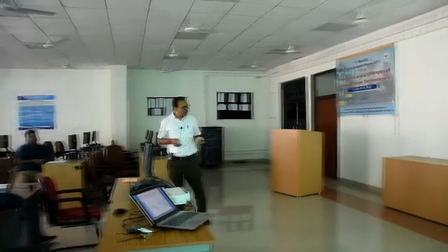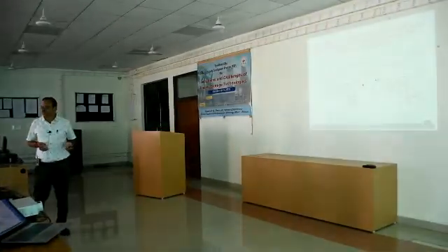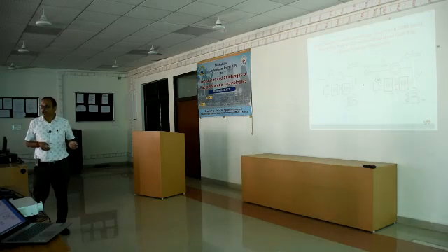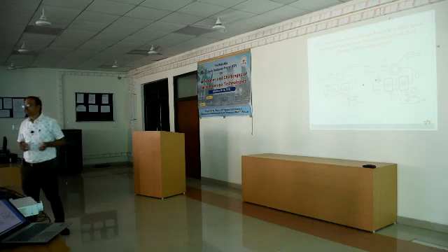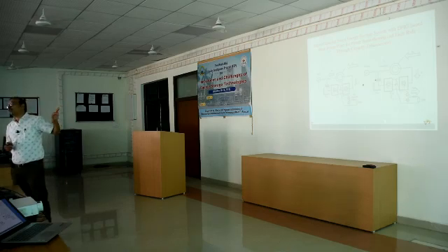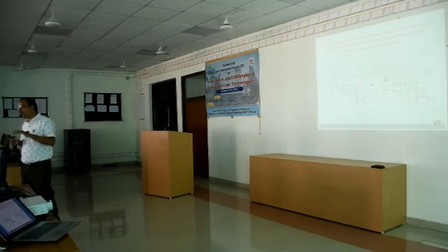So basically, during this time period, your energy storage system is trying to store the energy which is generated by your wind plant, and the stator and the rotor converter are utilized to inject a larger amount of reactive power to your grid, so that your system will remain sustained in the grid supply.